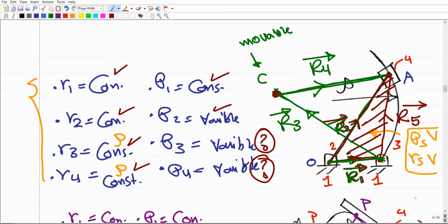How can we find this carrier acceleration? We said that we have to connect R5. If we decided to work over this loop, which is this one, we're going to end up with the carrier acceleration. So for this problem, although it is a direct contact problem, it is not advised to work with loop R1, R2, R3, and R4. If we did so, we can only solve for the velocity, and we're going to struggle in finding the acceleration.